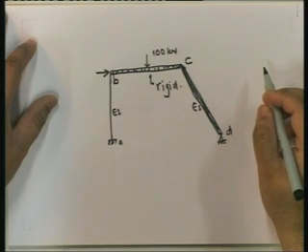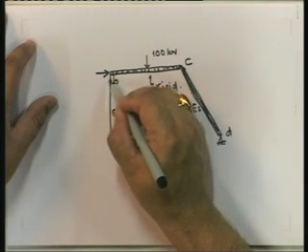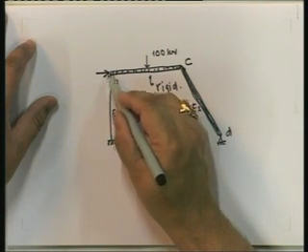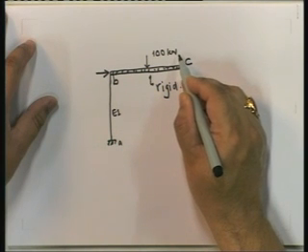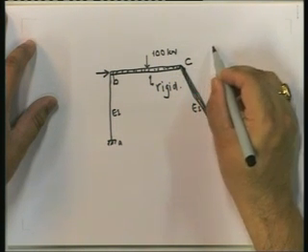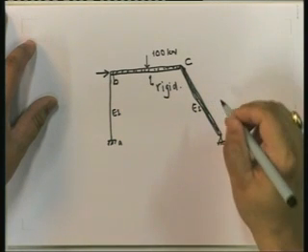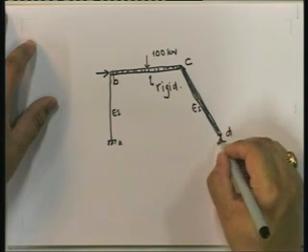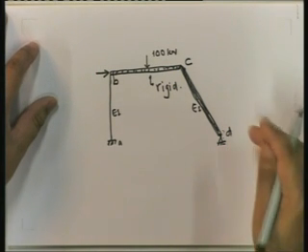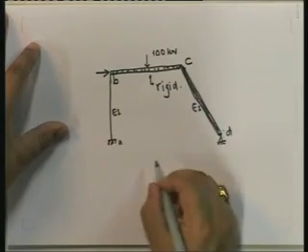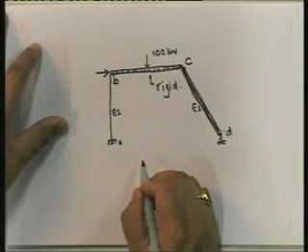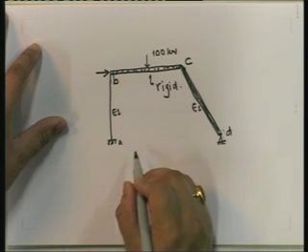Can you have a rotation at this point at B without this? Well, think about it. If this rotates, then this has to go up. If this goes up, then the only way this can go up is by this moving, and if this moves, it moves horizontally. So therefore, the 2 degrees of freedom actually are this and this, but this is no longer a degree of freedom. So let us prove to you that this is actually a single degree of freedom system. And for that, let us go through the steps.